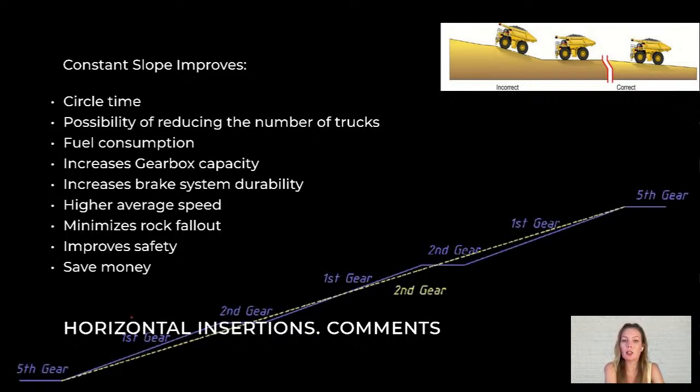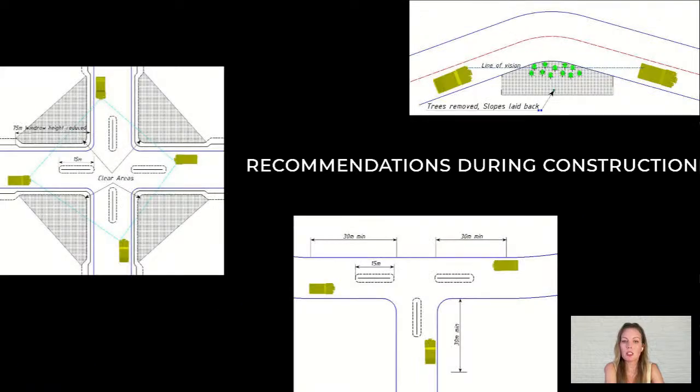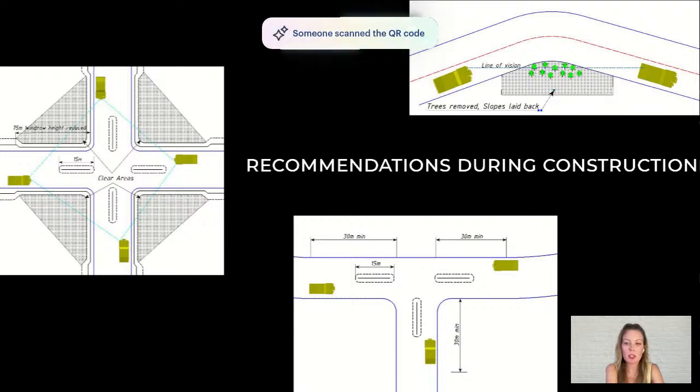Since we already touched on the topic of visibility, let's explore it further. This slide shows the conditions for designing the turning parts of a technological highway and different types of intersections, as well as key aspects of their formation. So let's break it down. First, any high vegetation that blocks the driver's visibility along the road needs to be cleared to ensure maximum visibility. This is especially important when navigating curves on the main road.